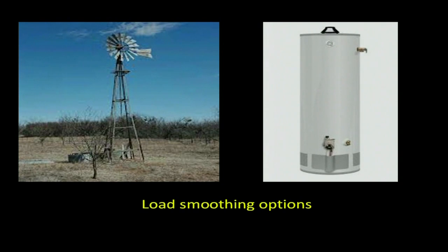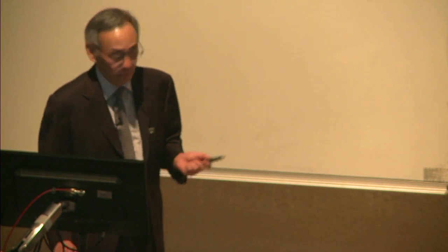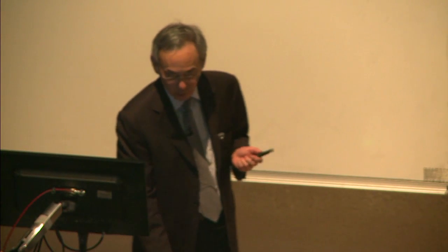And then you can actually adjust a hot water heater, especially a large one, this is a residential one, to go up and down by, let's say, 4 or 5 degrees C. It gets to be significant energy storage when multiplied by a lot of water heaters. And then a trivial technology says you don't scald yourself, by just having a temperature sensor as the water comes out to do a little premixing with cold water. Again, remember, electronics and actuators are very inexpensive. And so this becomes energy storage, but it's a different energy storage.